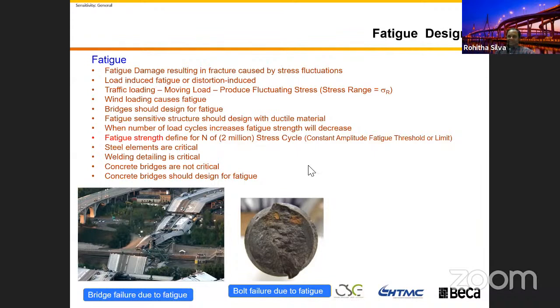But if you design cable stayed bridges, bridges with stay cables, I think the wind loading causes a significant impact on your structure, especially cables and other things. I think that causes the fatigue. So you need to check that one, because these are special conditions. Like when you attach a sign lighting pole onto your bridge, the wind loading causes fatigue. Yeah, it's similar to the sign structure.